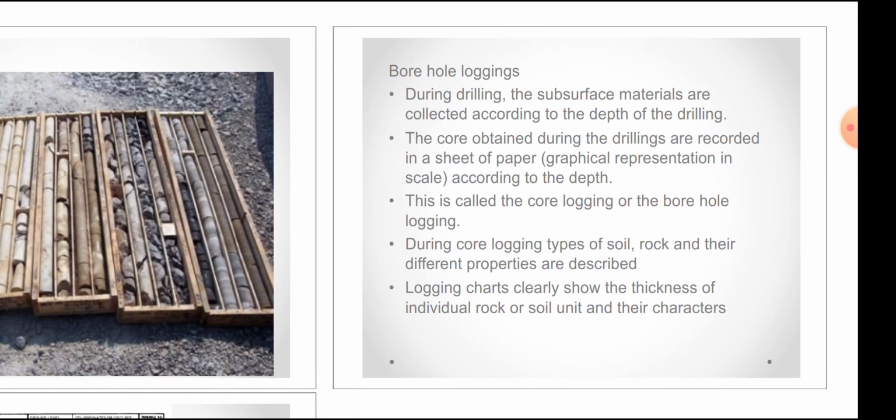Borehole logging. During drilling, the subsurface materials are collected according to the depth of the drilling. The core obtained during drilling is recorded in a sheet of paper, graphical representation in a scale according to the depth. This is called the core logging or the borehole logging. During core logging, types of soil, rock, and their different properties are described. Logging charts clearly show the thickness of individual rock or soil unit and their characters.